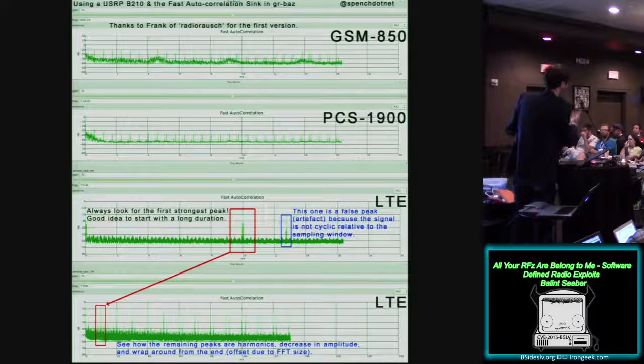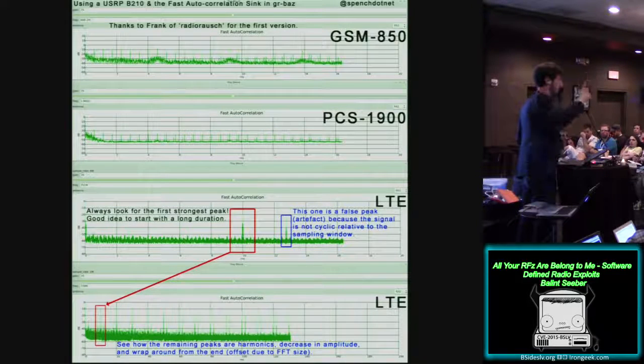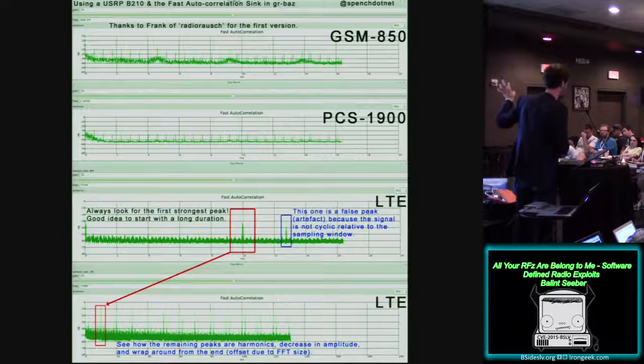And so if you have some unknown signal, you can put it into something like this, and if you know the standards, you can say, oh, well, that's repeating at this rate, or that's repeating at that rate. If you were to hook this up to GPS, you would have a peak sticking out at 1 millisecond, because that's the rate at which their CDMA code wraps around for the civilian access code. So it's another little hint about what a wireless system is doing. So some cool tools that you can use just to give you a flavor of what's going on.